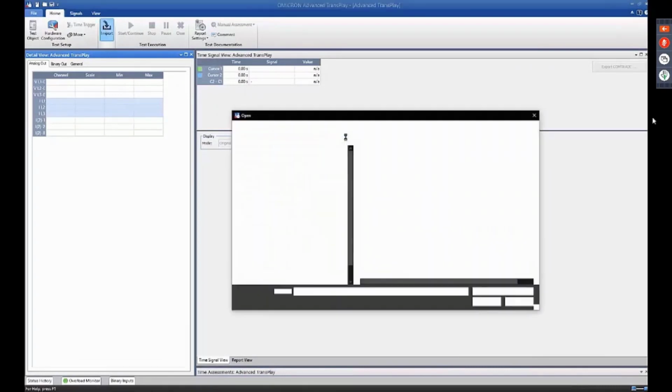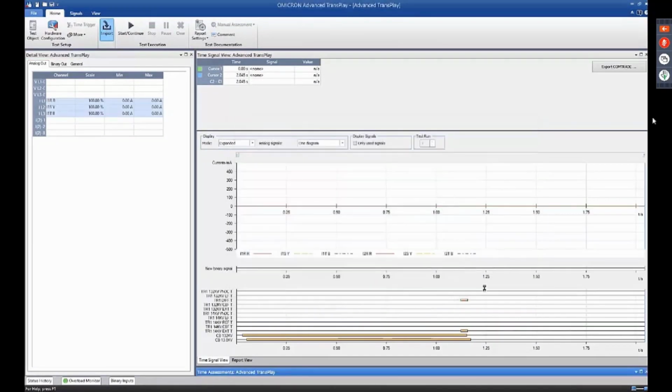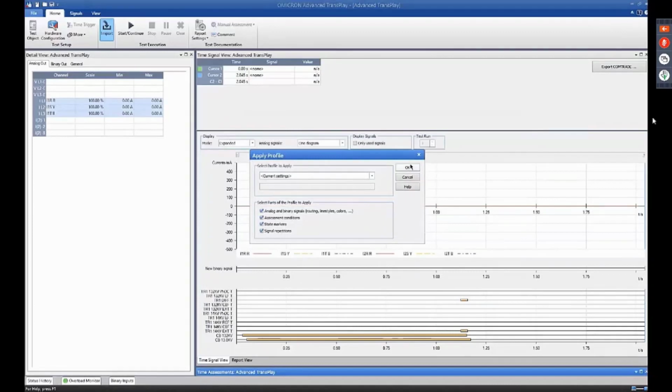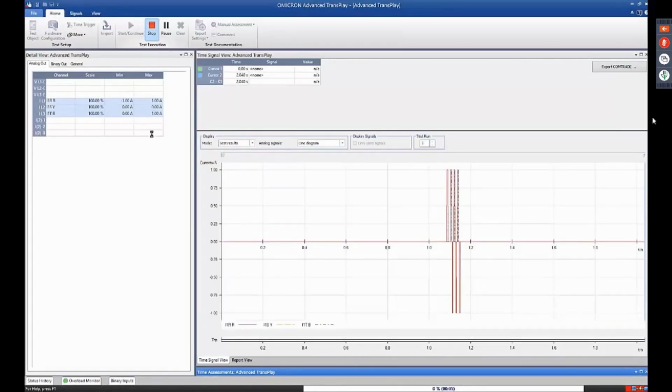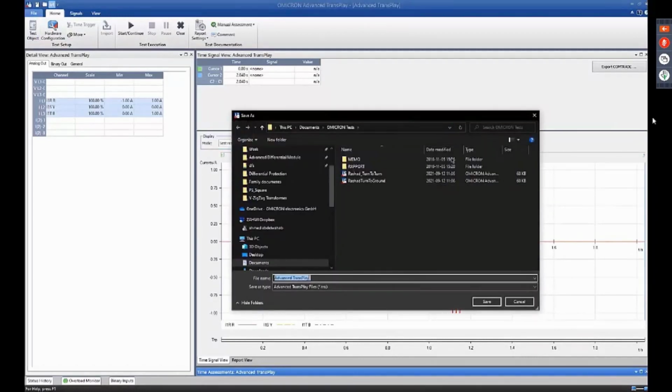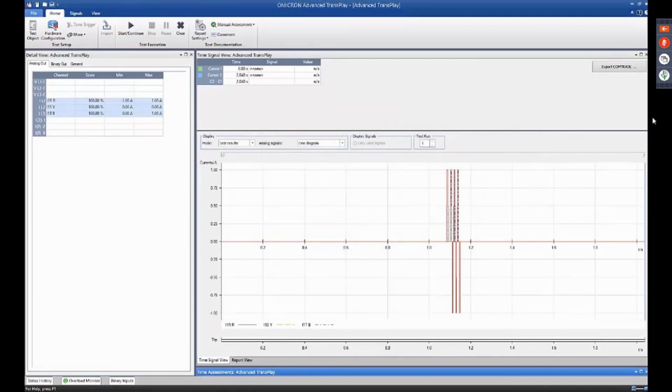Now we will import the Comtrade file. We can start the play. Now the CMC is injecting the fault on the protection relay, and we can see the behavior of the relay. We can monitor the LED, and we can check the Comtrade file again from the protection relay itself, and so on.